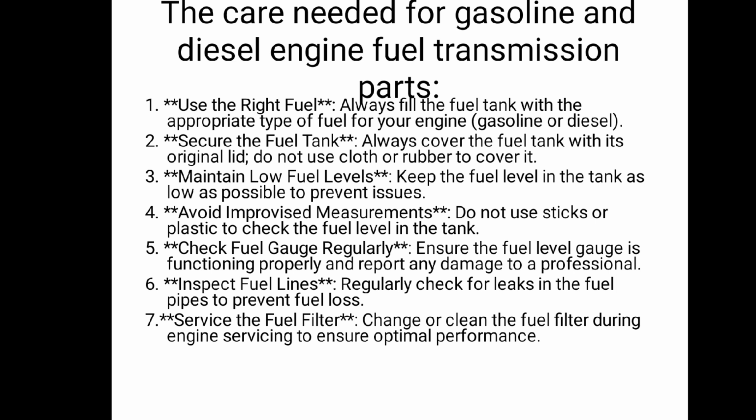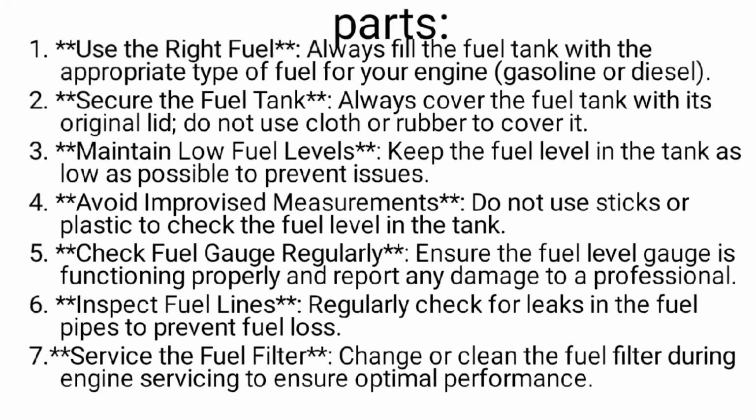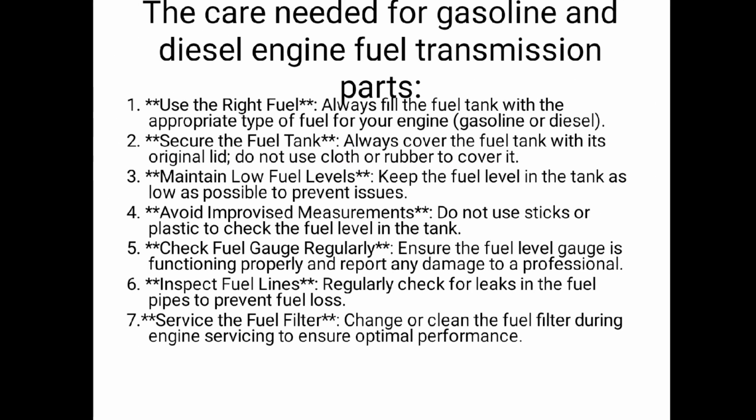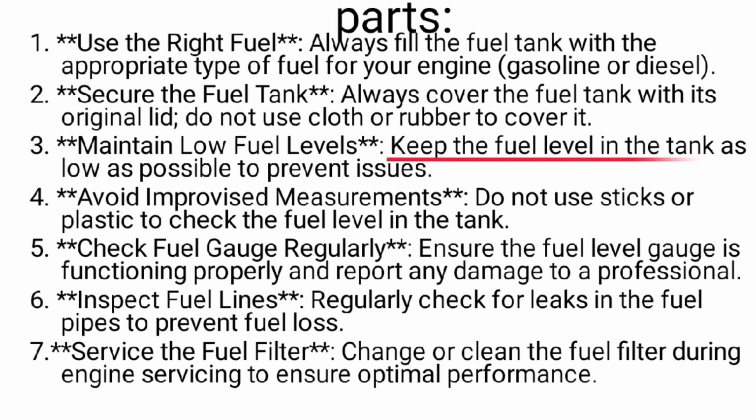Gasoline engines require gasoline while diesel engines need diesel. Using the wrong fuel can cause severe damage and costly repairs. Next, ensure that the fuel tank is always covered with its original lid. Avoid using makeshift covers such as cloth or rubber or anything, as these do not provide a proper seal and may lead to contamination.